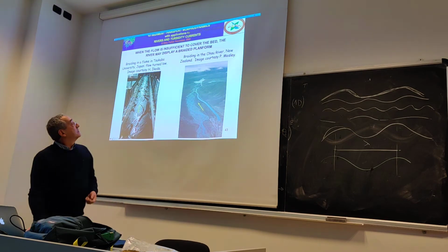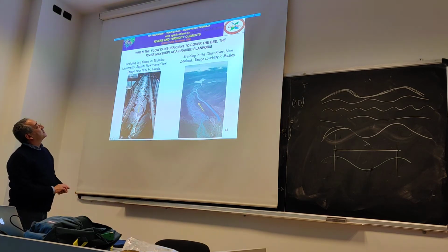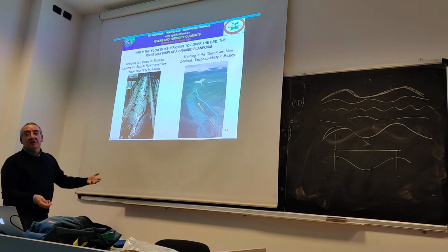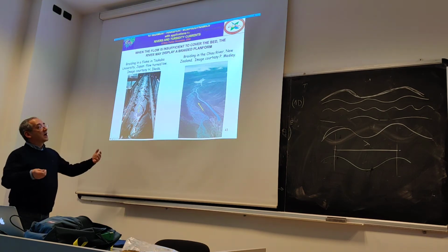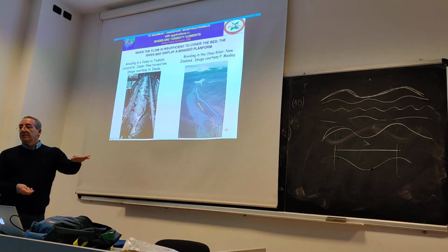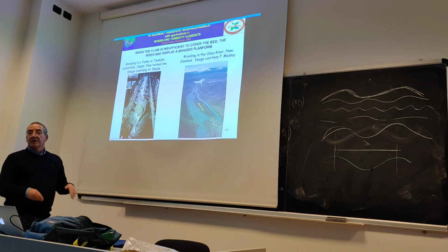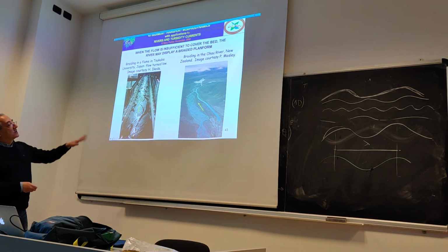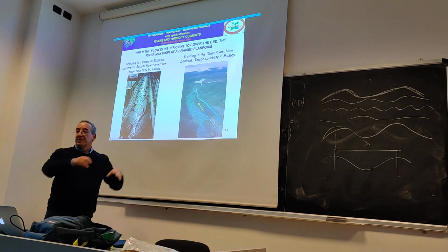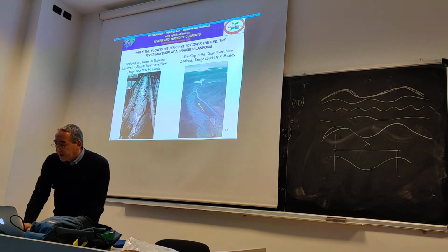This is a braiding. So it's a situation in which you are at low flow. During high flow, you have the formation of that multiple row bar bed. Then the flow goes down, and what comes out is typically a braided system, a connection of many channels in the plan.